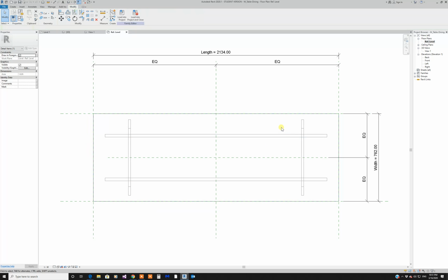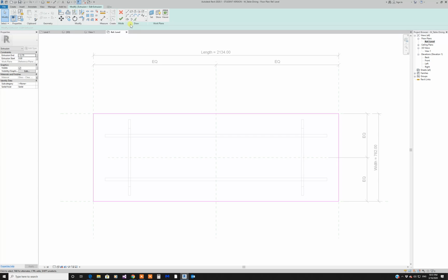this is the plane. I'm not selecting the plane. I want to select, okay, so I'll select the top of the table. It's based on an extrusion, as you can see here, Edit Extrusion, and I may want to add, okay, 80 here. Okay, make it straight here. Okay, and I'm just going to mirror this again to the other side.